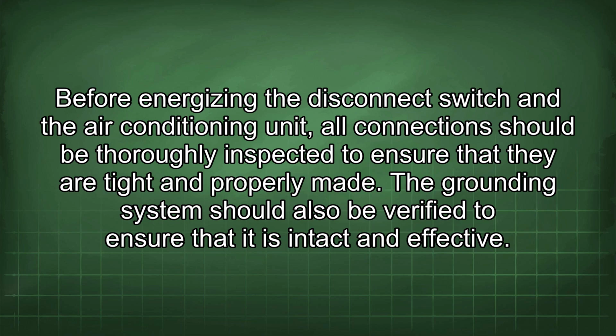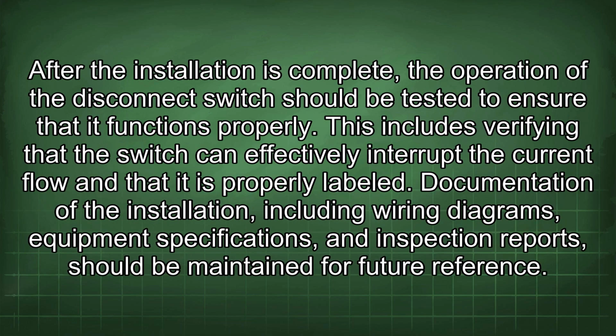Before energizing the disconnect switch and the air conditioning unit, all connections should be thoroughly inspected to ensure that they are tight and properly made. The grounding system should also be verified to ensure that it is intact and effective. After the installation is complete, the operation of the disconnect switch should be tested to ensure that it functions properly. This includes verifying that the switch can effectively interrupt the current flow and that it is properly labeled.